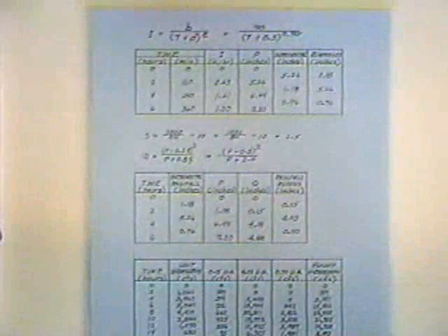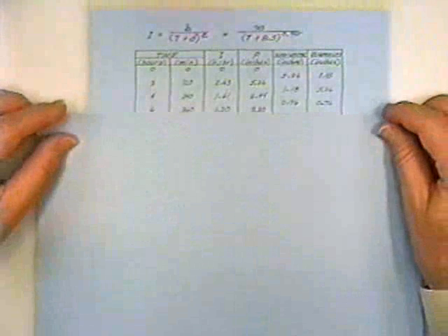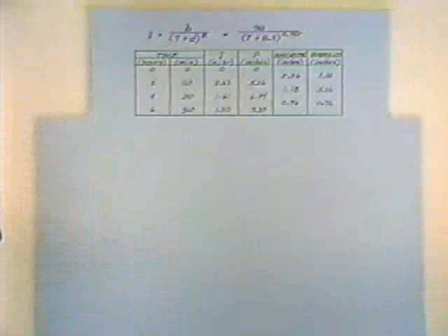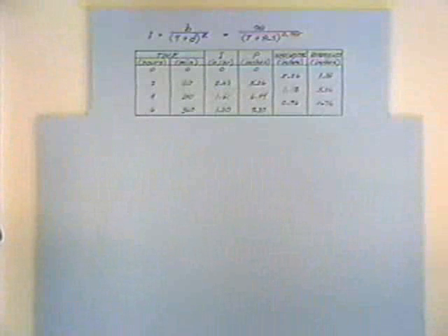And so we're putting together several different things here. The first thing we need to do is develop rainfall data. If you'll just focus on the first set of computations, we're using a 6-hour rainfall duration. We've got a unit hydrograph for a 2-hour rainfall duration, and so we're going to compute rainfall volumes for a 50-year recurrence interval design storm using a 2-hour time step.